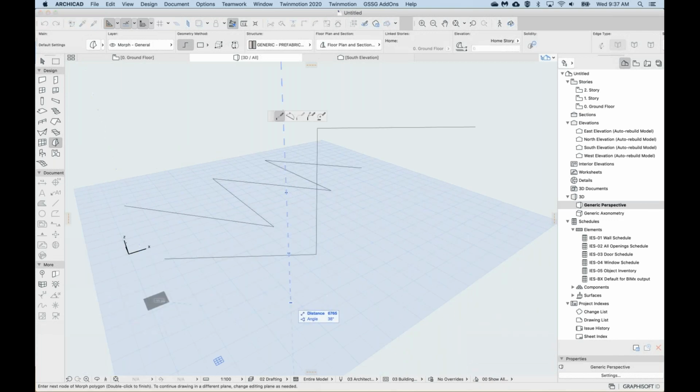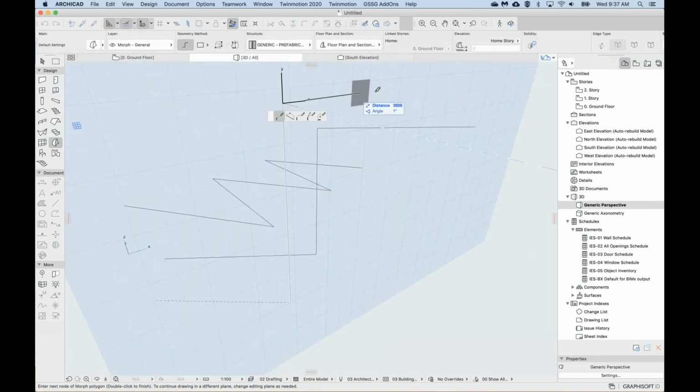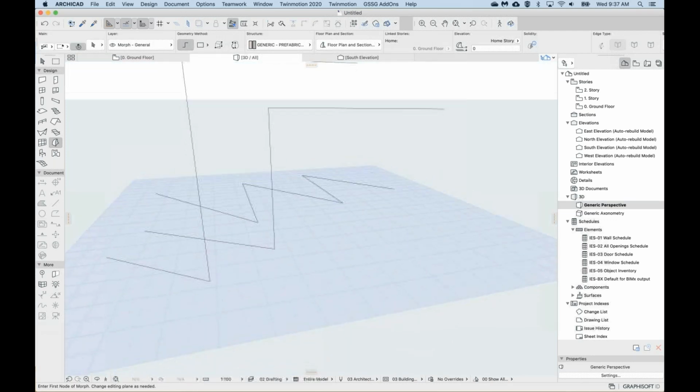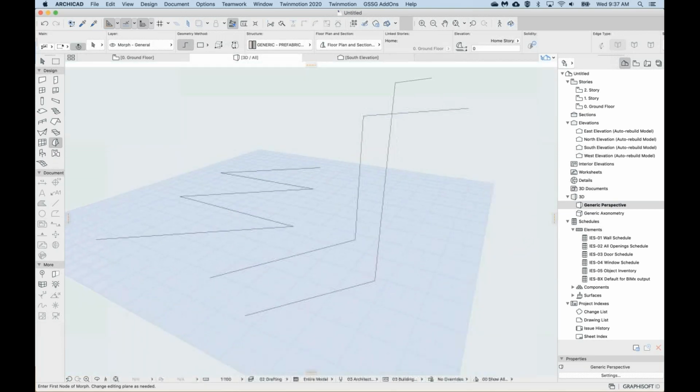So I just did 2 clicks in 3D. So 2 clicks, move my cursor to the Z. Once the Z turns yellow, hold Shift, move my cursor up, click, and this then moves the editing plane upwards, and then do another click somewhere along, say, the X-axis, just to be able to move our cursor in the XYZ coordinate system.